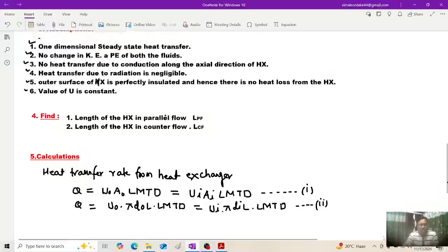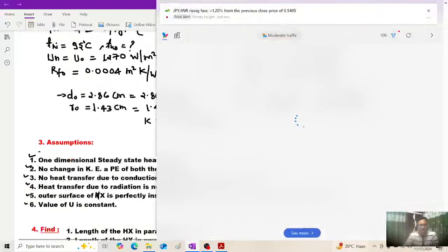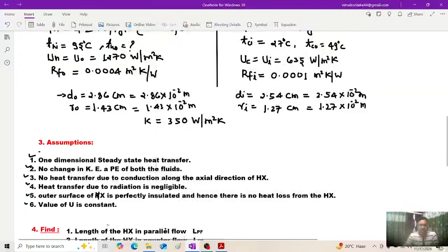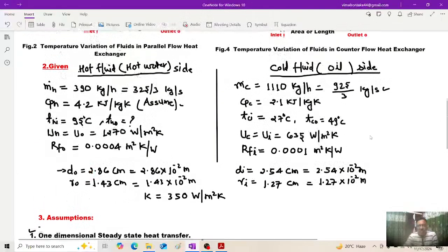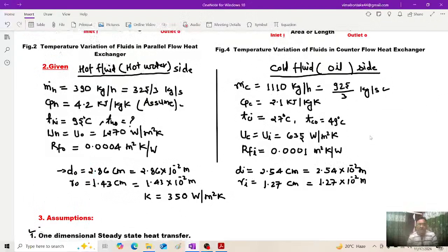Now before moving further, one more important point worth remembering while dealing with the LMTD method for analysis of heat exchanger. The LMTD method can be satisfactorily used only and only if all the 4 temperatures of hot and cold fluids are known to us. In our case, inlet and outlet of cold fluids are given.